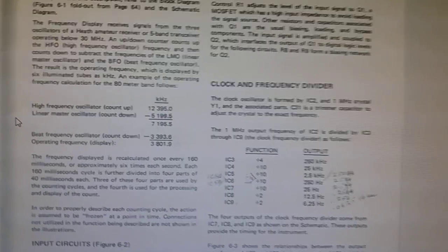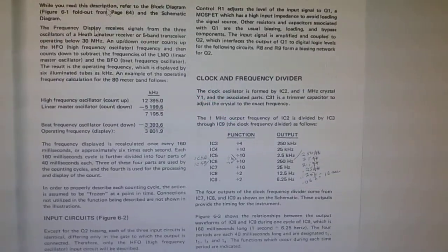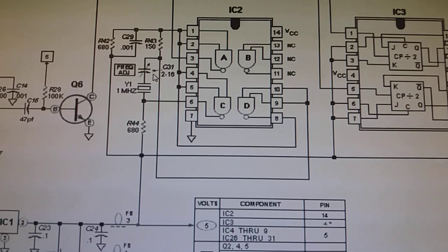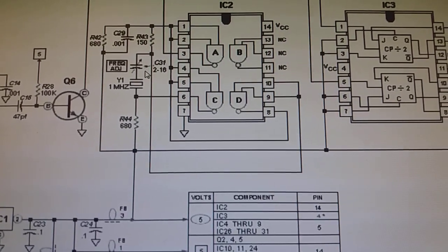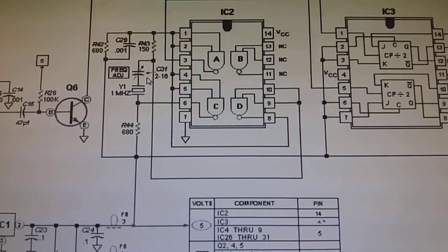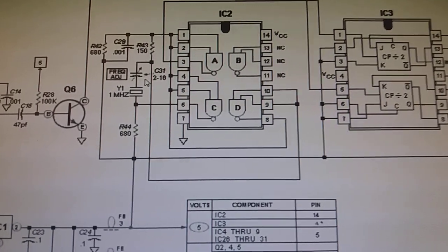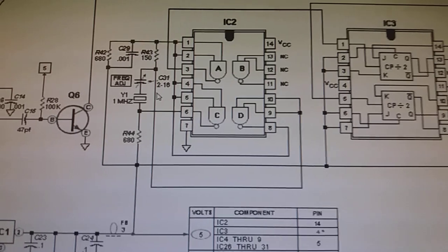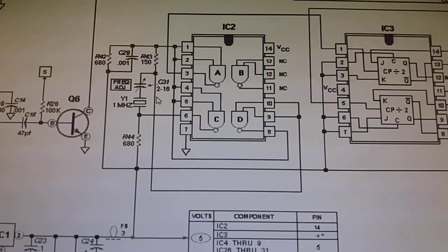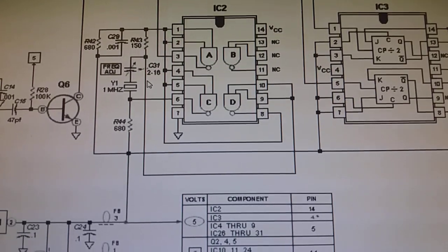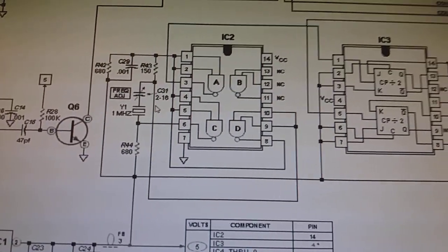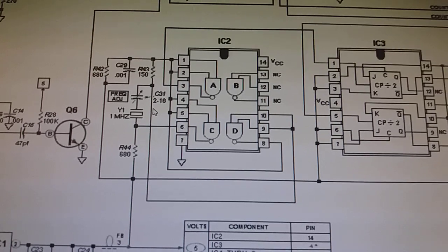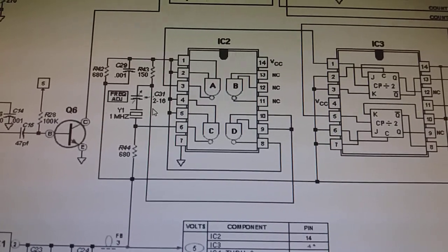And so I'm fiddling around again with the crystal frequency at this point, and I'll try first to put a smaller value of capacitor there. Let's say I'm gonna either remove this capacitor and see if I have any 1 picofarad capacitors. They're more difficult to find, but I might have some, and see how it goes, if this 1 picofarad of difference does any good or not.